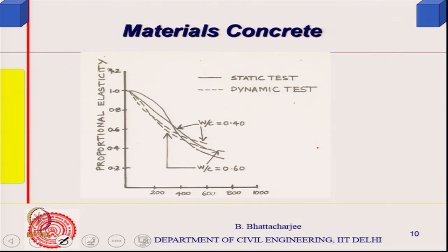So, that is why you see this kind of behavior, and therefore the modulus of elasticity, which one would need in design, if somebody is doing a fire design, then you can see that the relative value of modulus of elasticity reduces in this manner, some manner it reduces.